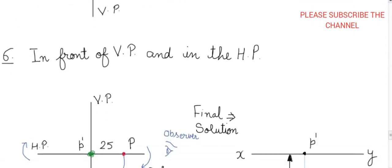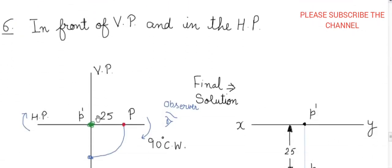So now move to the sixth case, just opposite of that. The point is lying in front of VP but in the HP. This red dot shows point P is 25 mm in front of VP and in the HP. When the observer sees this point, the front view is projected on the origin and shown with the help of small p dash. Okay. Now the top view. Top view will lie where the point is lying itself, there. The point is also lying on the red dot. So the top view is shown already where the point is.